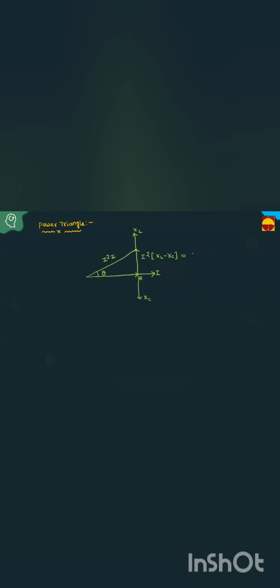This you can write like this now: I square into XL minus I square into XC. What is I square into XL? QL. What is I square into XC? QC. That formula is already known. This is I square into R, which is P. What is I square into Z? S. This is which triangle? This is the power triangle.